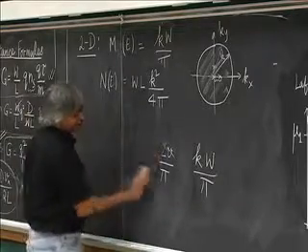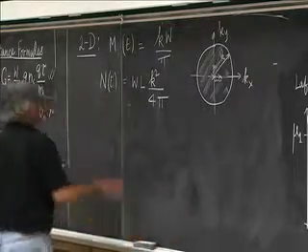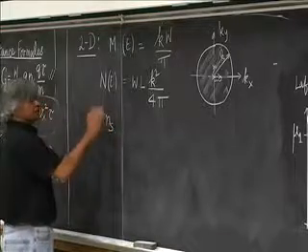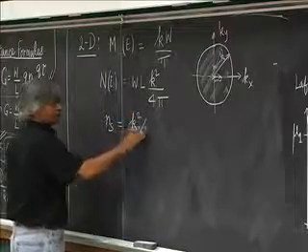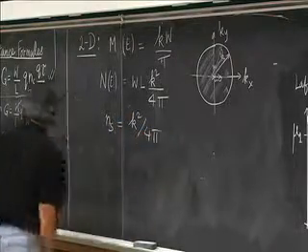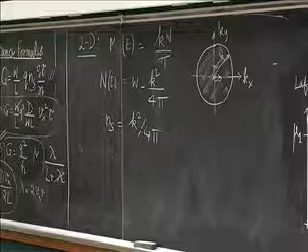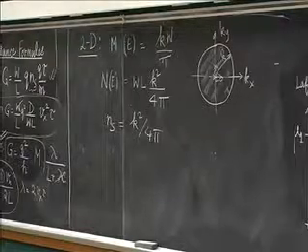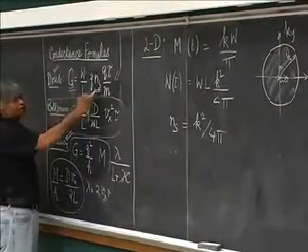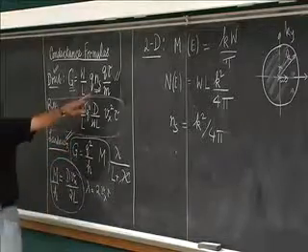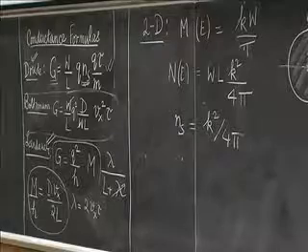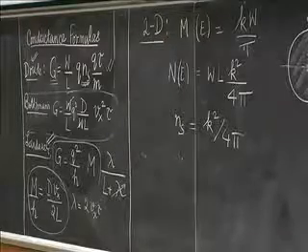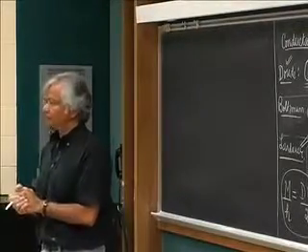So you could write the electron density per unit area, this is N divided by WL, as k squared over 4 pi. Okay. So if you look back then, in this Drude formula, conductance is proportional to Ns, and that thing is what you interpret as mobility. So anytime you see any data on conductance, first thing you do is divide it by the electron density that you have measured and plot it, and then ask the question, now what is this mobility?